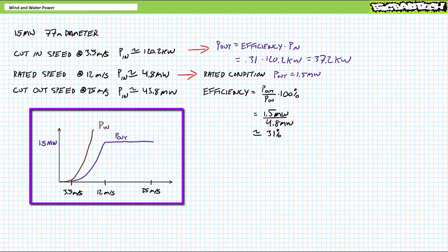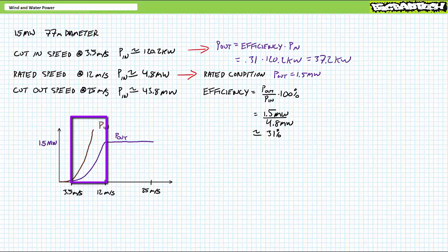Pretty much all wind turbine power curves look like this, so you should probably familiarize yourself with its shape and the reasons it takes this recognizable form. You'll note the characteristic steep ramp up from the cut-in to the knee at the rated speed, and the flat line from the rated to the cutout speed, at which output drops off.